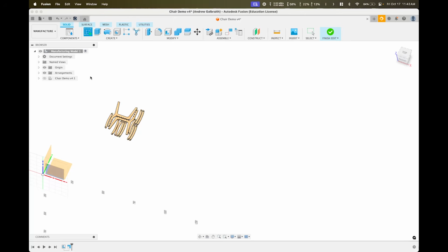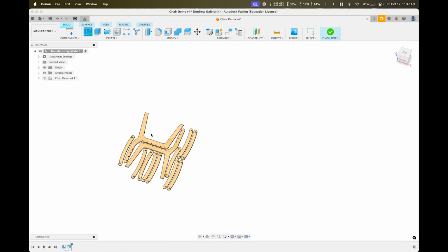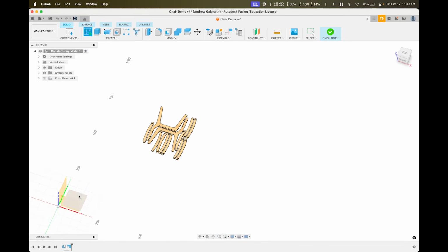One thing to think about is, while you could just click on the top surface of one of these that you have laid out, that will project the geometry of whatever face that you select to your sketch, which right now we want a super clean sketch. So I don't want to have that projected into my sketch. So that's why I'm creating it on the origin. Does that make sense at all? I want this sketch as clean as possible. I want to only have what I want on the sketch, because we're going to export this sketch. And when it comes to exporting sketches, it can be a little funny, so you want the cleanest result you can get. So we're creating the sketch on this plane rather than on one of these planes here.